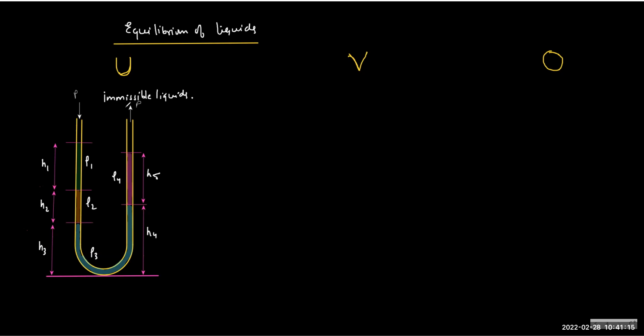The best way to solve a question like this is the dive in, dive out method. I have named this method something funny. What you need to do is dip inside the tube from one of the ends. You can choose left or right, it doesn't matter. While you are descending, keep on adding the pressure till you reach the bottom. And while you ascend, subtract the pressure till you come back to the open surface at the other end of the tube. Then you can write the equation.